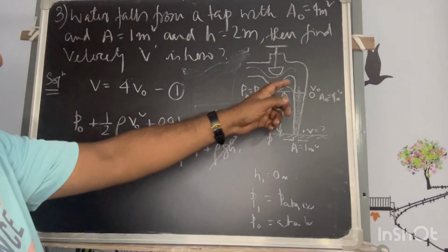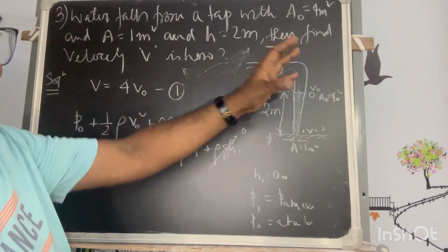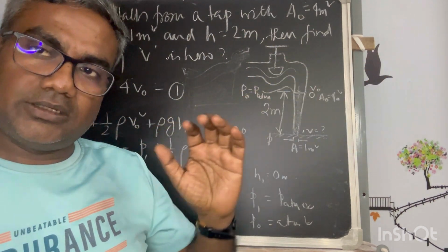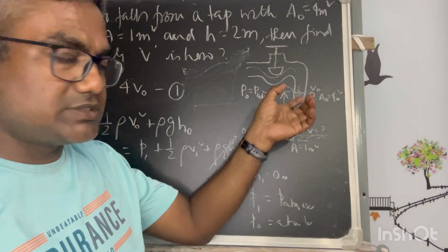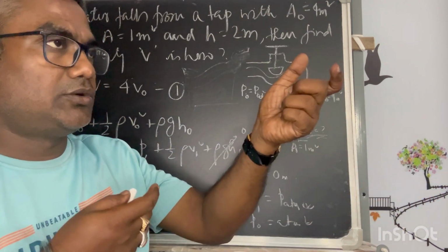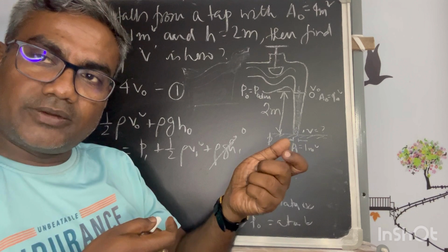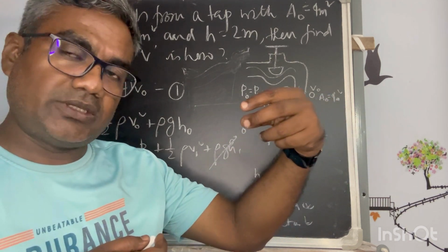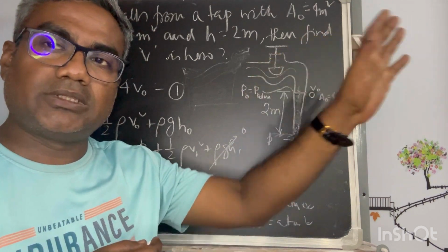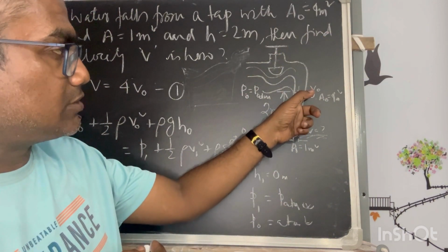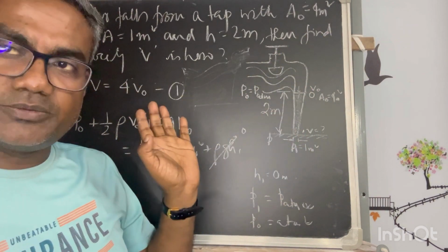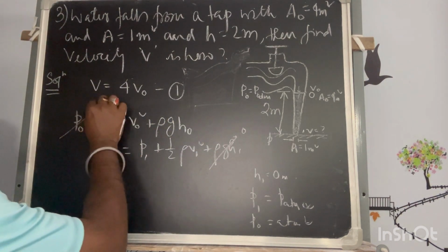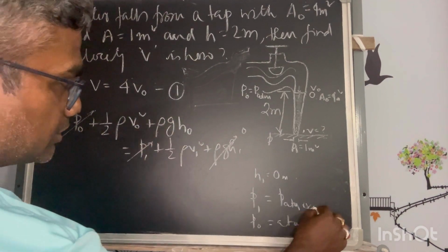So for any such case where the flow is not flowing through a closed conduit or duct, if it is atmospheric flow, that means when you are ejecting some water through a fire hose, the tip of the hose, when it is reaching, from there it is releasing, it is coming under atmospheric pressure. The pressure here is also atmospheric, here also atmospheric. Understand? So this pressure energy, both are same, so we can nullify, because both are atmospheric pressure.